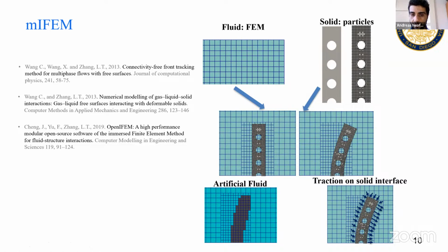So now when we solve the entire fluid domain, we have this part that behaves as much as possible as the solid. Now, the way the solid sees the fluid is as an FSI load on the interface. Since we have the particles at the interface, we can apply the loads directly at the boundary on the solid side.